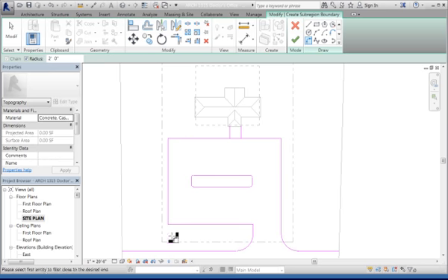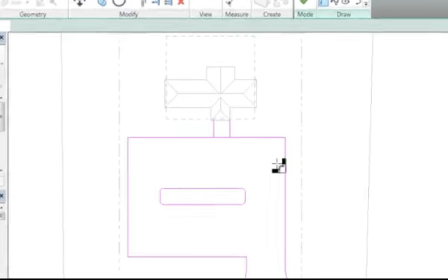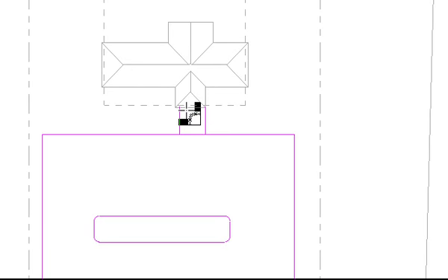And these are outside, so you probably don't have to do them. But the other thing, remember whenever you're working with these pink lines, all of the lines, nothing can overlap, and it'll give you an error message if you're doing that. So it all has to be one enclosed space. So I need to break this one. I mean, technically there would be a step up here, but I don't think we need to worry about that at this stage.